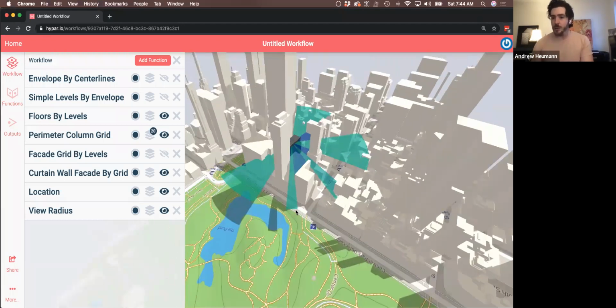In Revit, you can absolutely produce native Revit elements with this. At the moment, you might need to write a few custom converters just because we haven't built in support for every imaginable Revit element type yet, but that will come eventually. But you can also download your current workflow as IFC. So that's one way to get stuff into Revit as well. And then as far as the Rhino context, currently the only thing that's supported is using Grasshopper to get that stuff out.